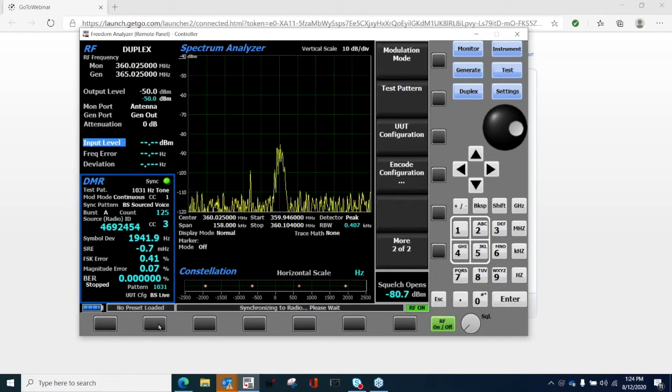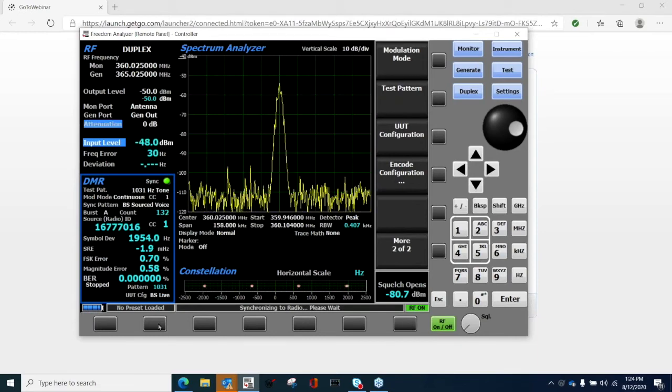The repeater starts synchronizing, and you hear a 1 kilohertz tone on the portable. This is transmitted by my R8100. The R8100 is using our interface to connect to the repeater, and then it repeats this information on your portable radio. With this, we should take some other readings on the DMR screen.